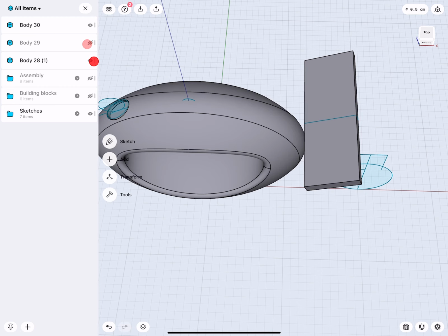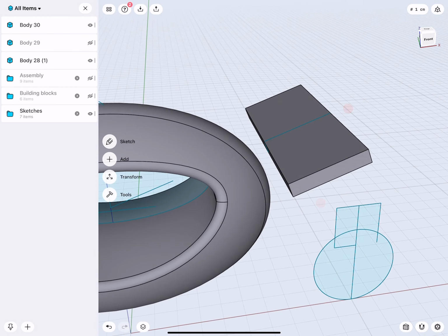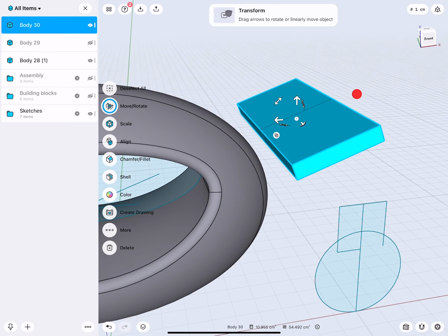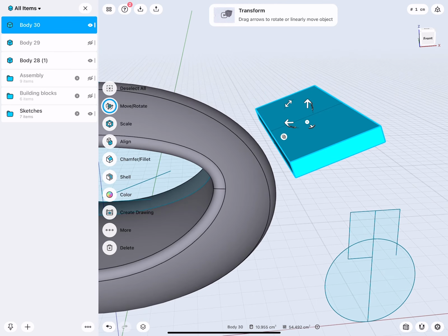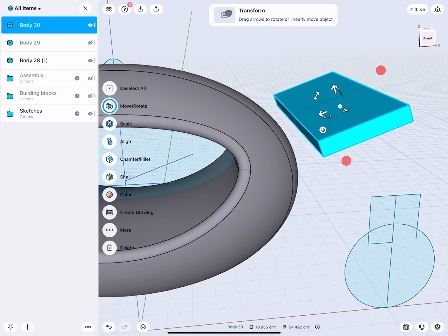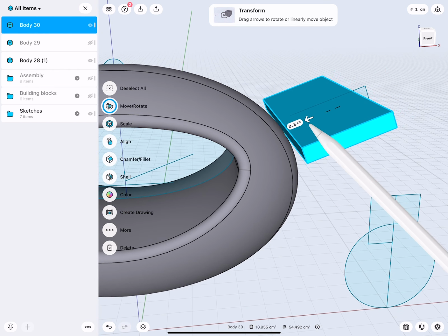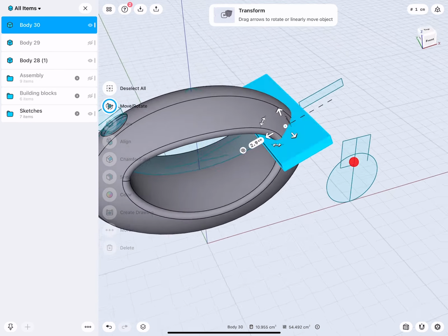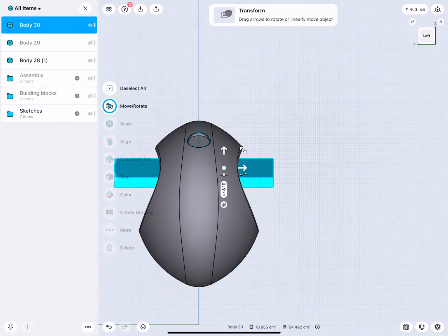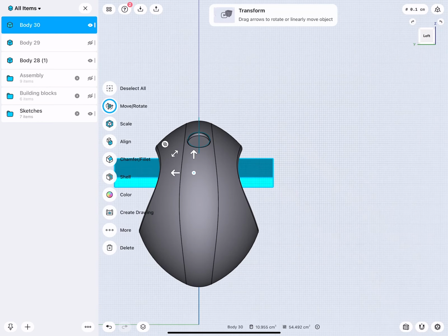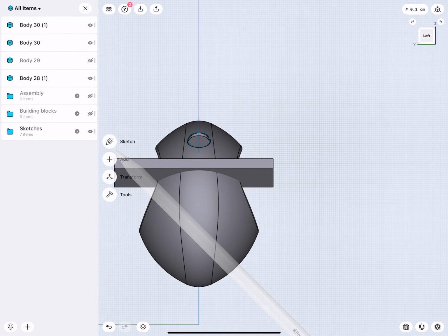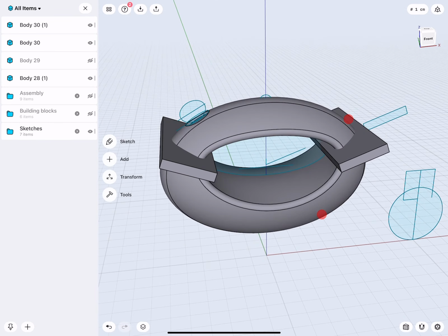And here is my body. Double tap. You see that the 3D widget looks straight up. Move it a little bit. You see how this now got reoriented, and now I can slide it down into my design there. Very nice. Go to the other view, double tap, and mirror tab there. So we made a copy of this.